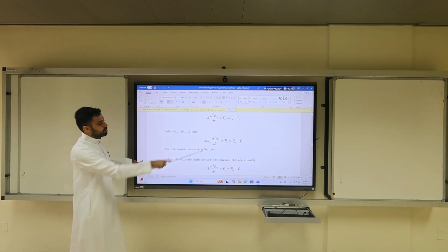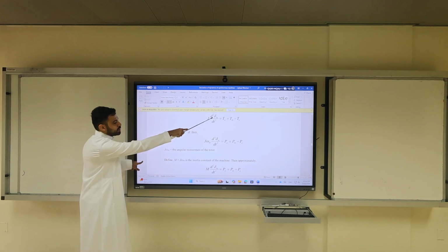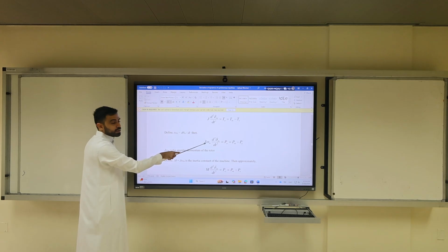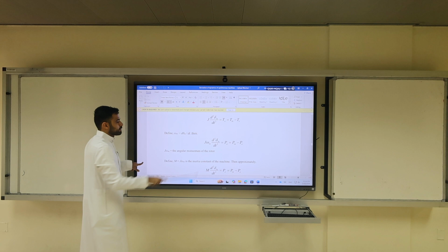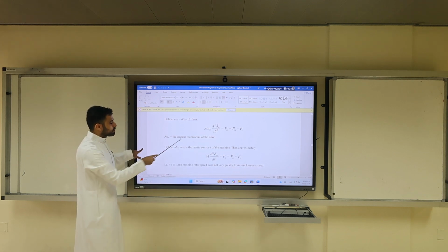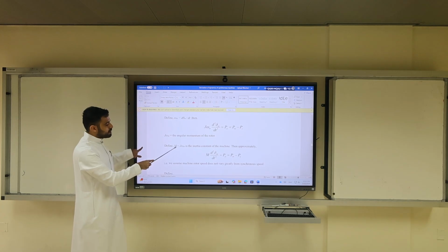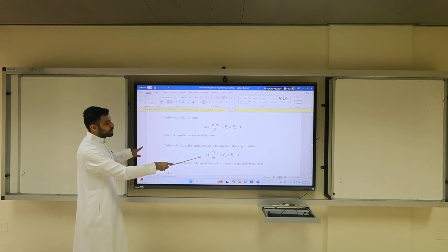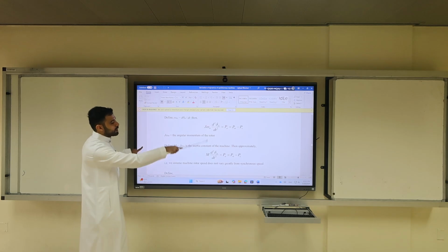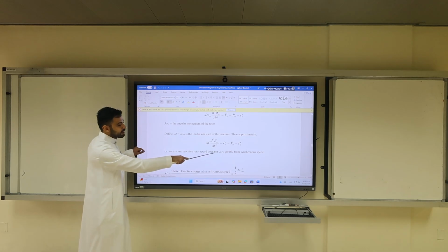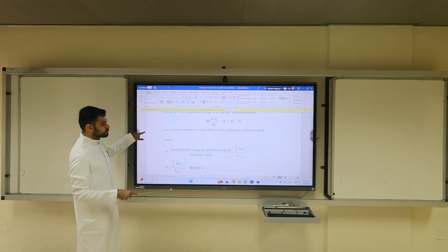Anybody can guess how we got this term? Oh, this is power. Yes. So multiply by omega, that's why we got this omega. Get it? Because we transfer from torque to power. So J omega m is the angular momentum of the rotor, defined by definition as M, J times omega, the inertia constant. Now if you substitute J omega m with M, you will have this equation.